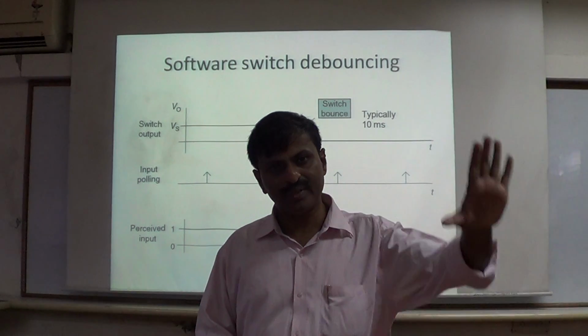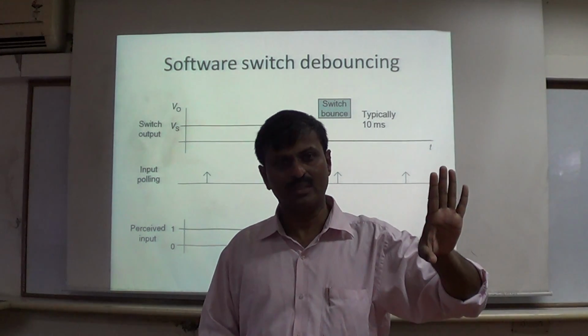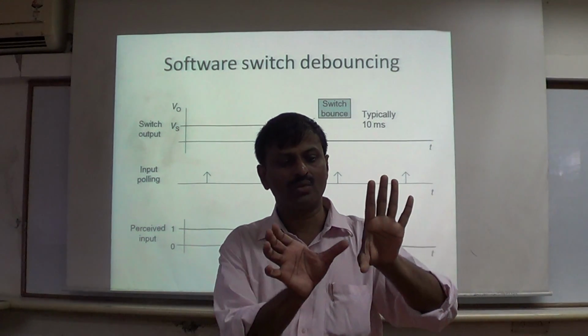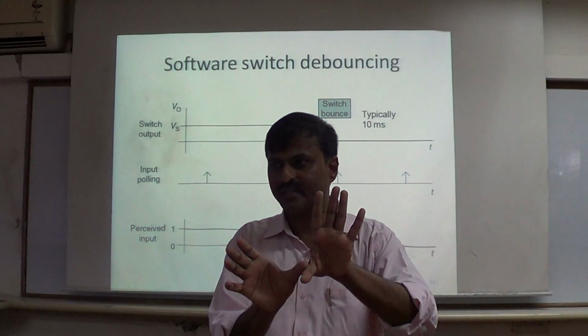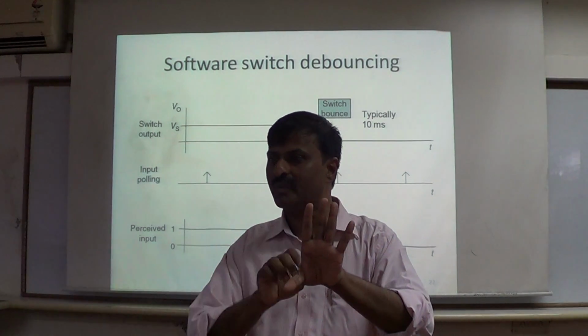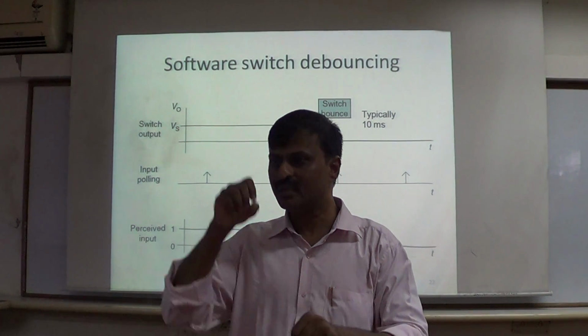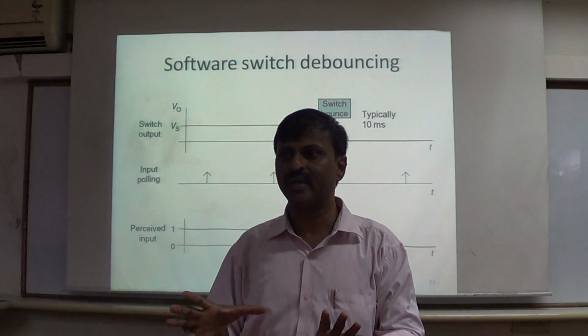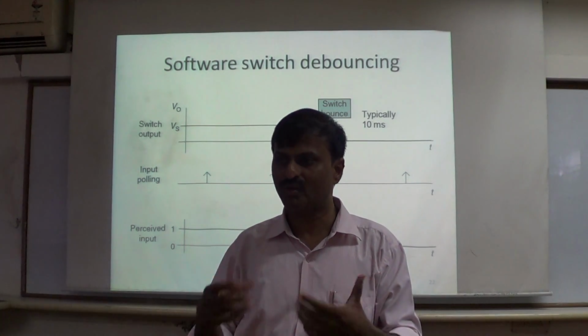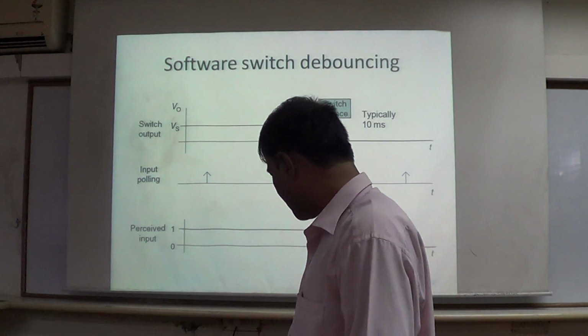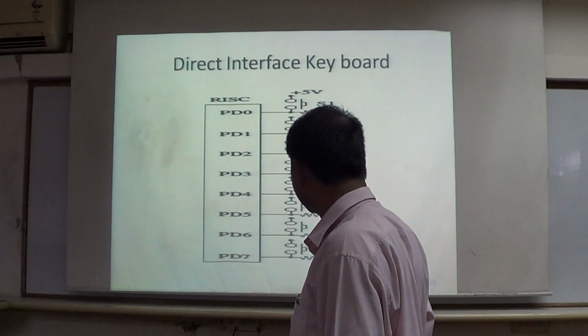You have recognized there is a key press. Then what do you do? Call a delay of 10 milliseconds. And then after 10 milliseconds, come back and confirm again: is the key really pressed? Yes, then it is confirmed. If it is not pressed, then it must be bouncing. Avoid that. So you must have some solutions to overcome these problems.